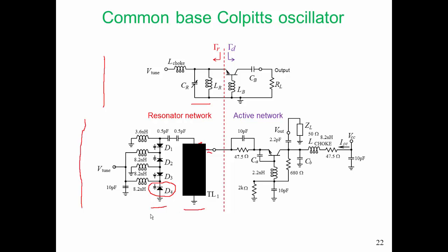So this stacking has enabled us to take our derivative of BR with respect to amplitude down to something very close to 0. And that is exactly what we needed to do in order to use that simplified Kurokawa oscillation condition.